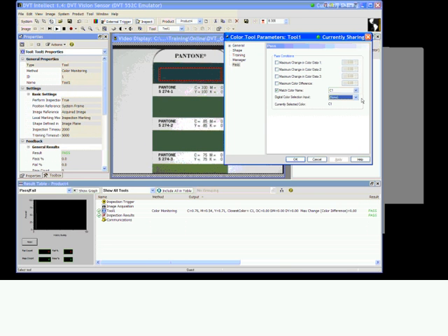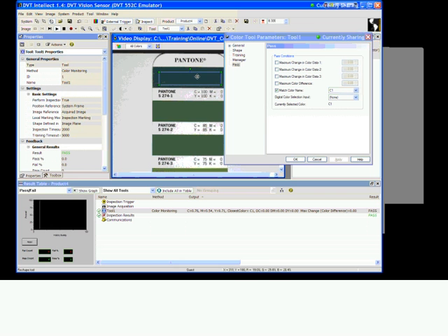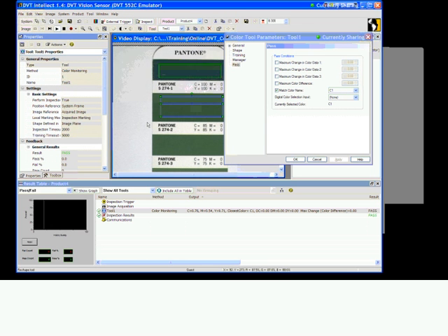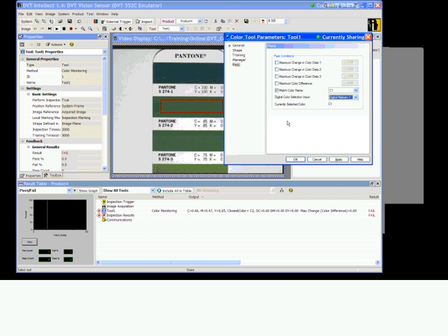And we can change that through a digital relearn. So if we change shifts, and now we're going to be looking at C2, I can change the expected color name by sending one of these digital relearn signals, and then on the next trigger, the next inspection, the camera would automatically switch between C1 and C2 and identify that, okay, now we want to look at C2 from now on until I change it again.